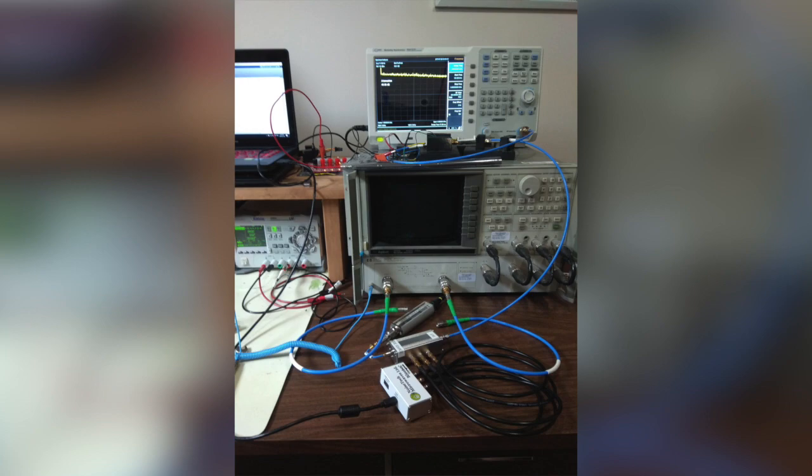It's actually recommended that it gets powered down or the port powers get turned off, because it can sweep power, and the power is quite high. And now that we're measuring noise power, the noise power is quite low, and it could actually present itself as interference to your noise measurements, which could reduce your accuracy. So this is the first noise measurement being done.